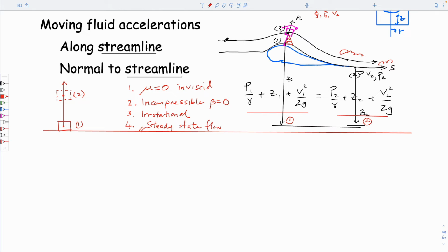Clearly, the particle of fluid that was at this point at second 1 is not here at second 10, it's gone somewhere else, but the overall flow system looks exactly the same. So it's not changing in time, so it's a static system. Even though the particles are accelerating through the system, in the reference frame that you choose, which is a static reference frame in this case, it's static.